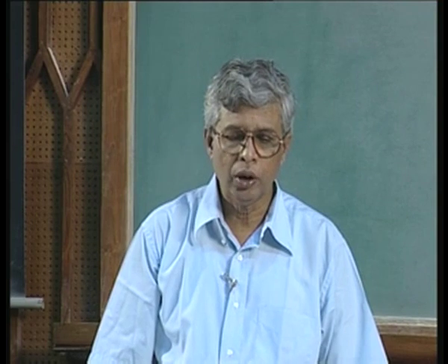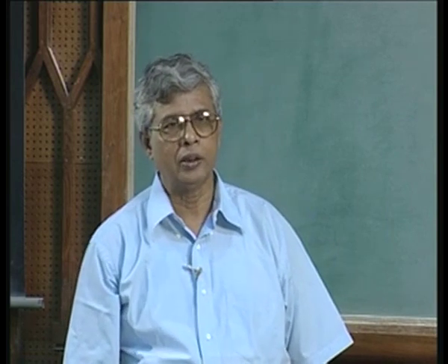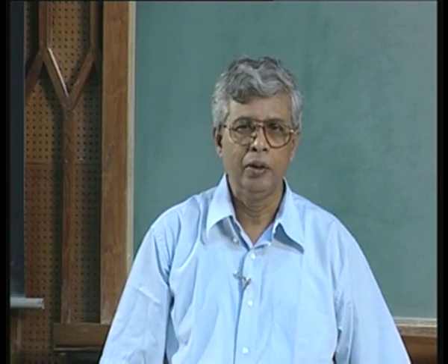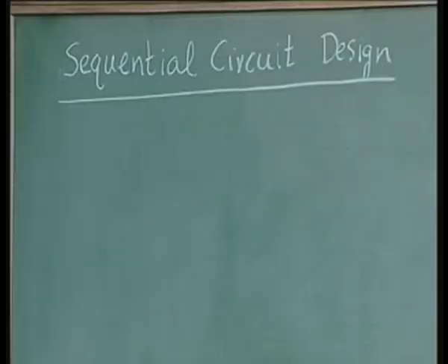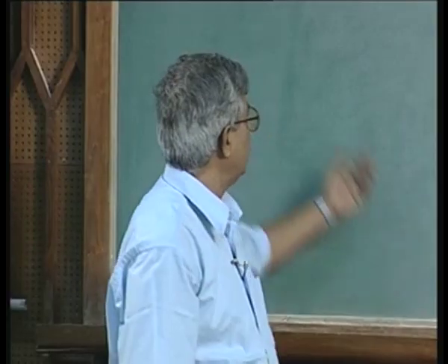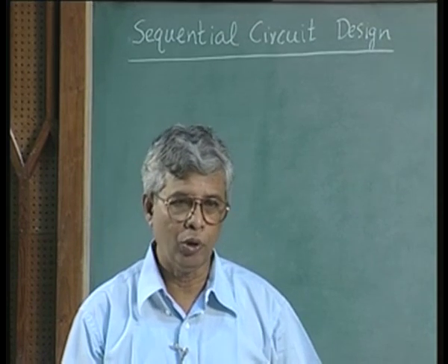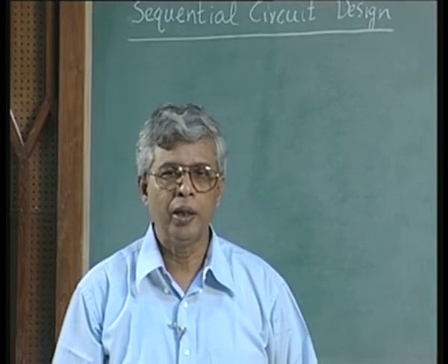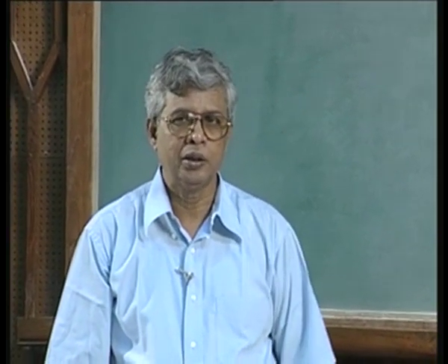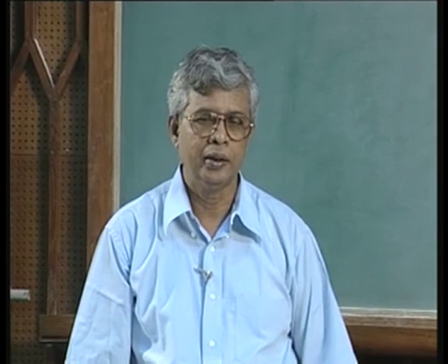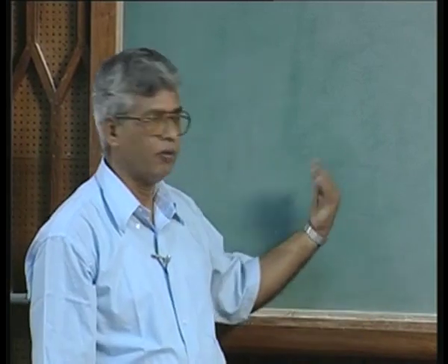Even though they are total digital systems, whenever a sequential component like a flip-flop is involved, the circuit is called a sequential circuit, even though it will have a combinational logic in it. So, today we will see circuits which will use both combinational and sequential elements. As I said, they are called sequential circuits, but they will have both combinational elements and sequential elements. Combinational elements can be in terms of gates and multiplexers, PLAs, PLDs, whatever, and sequential circuit elements will be flip-flops.